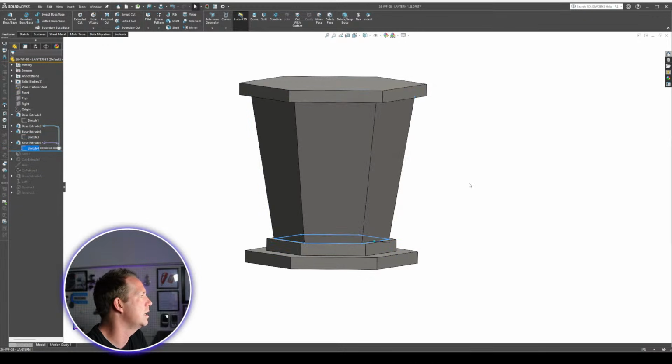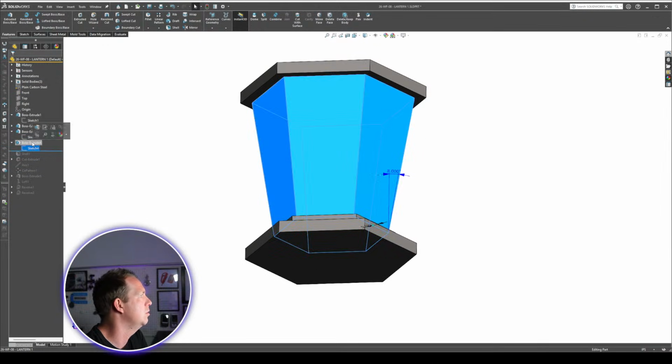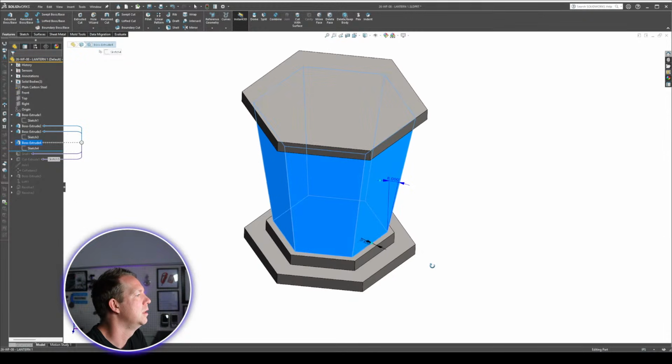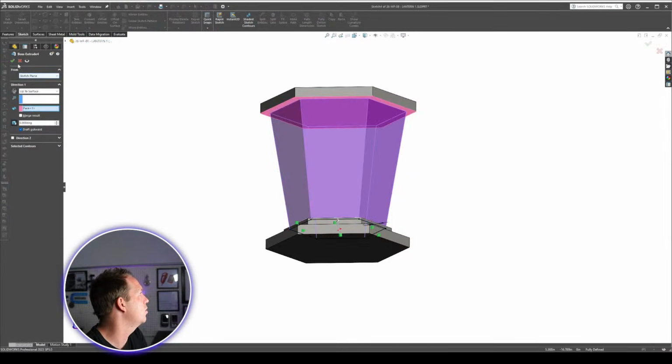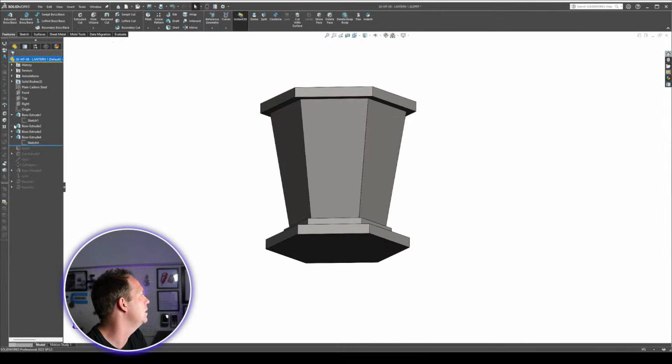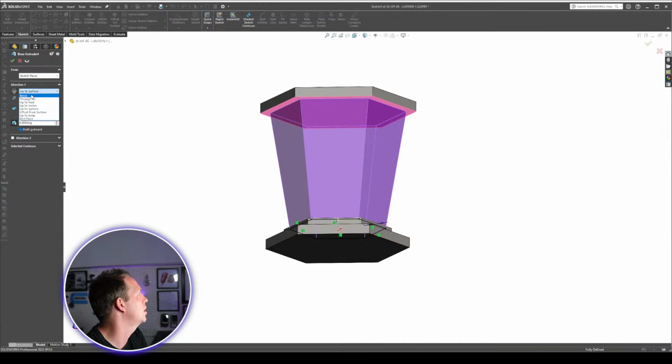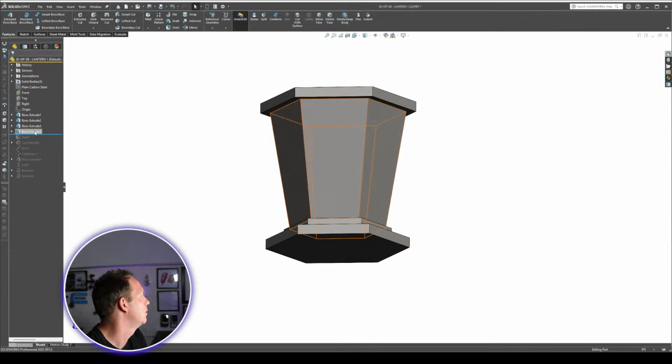So like I said, I didn't use a lot for this one. I knew the angle, the 8-degree angle. And I knew the bottom hex, so that is a simple extrude up. And I did the extrude. One way I could have done this quicker, I believe, is actually change the order of these two. So change this one to just go blind, 6 inches. And do that 1 second.